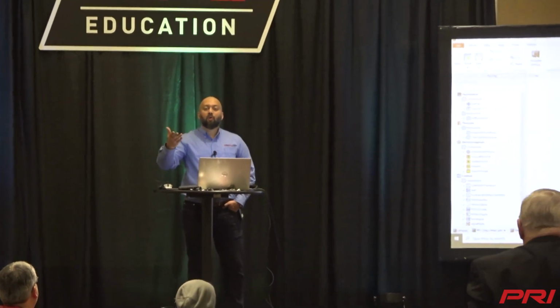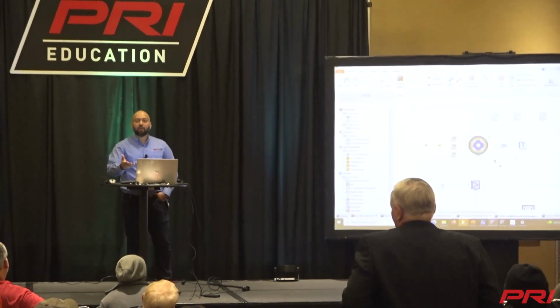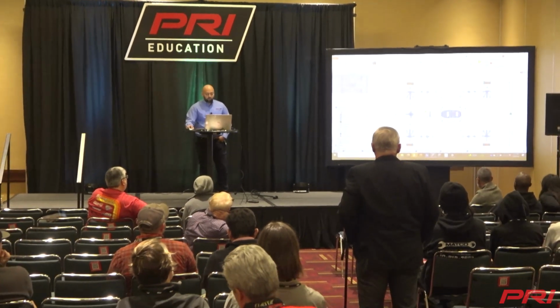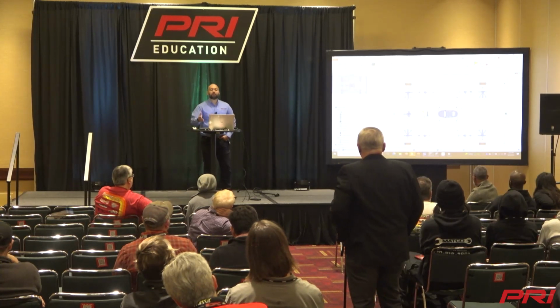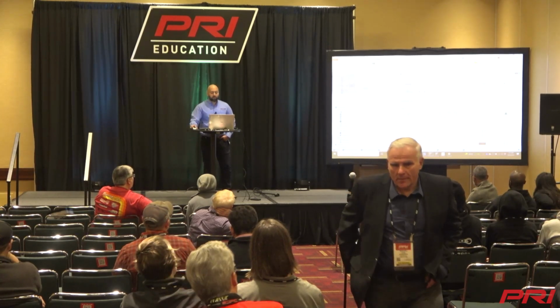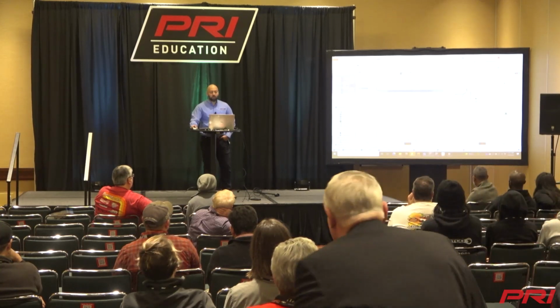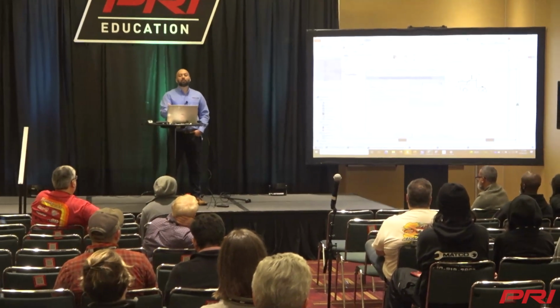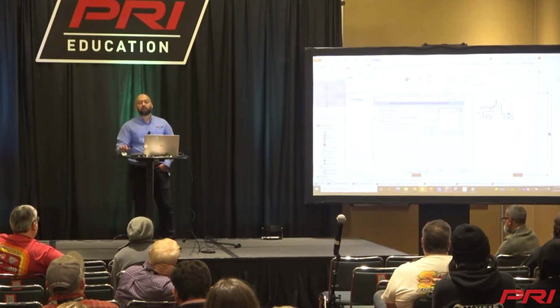Thanks for that question. What about drag coefficient? Drag coefficient is an input to the vehicle, and that's what determines the power it requires. So the question was the impact of drag coefficient on, let's say, a race car. In this case, rather than comparing two batteries, you just compare two drag coefficients. Right now I have 0.29. You can have, let's say, 0.26, and it will showcase how much faster your vehicle can go.